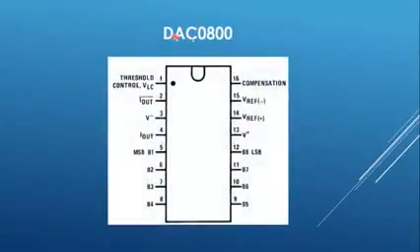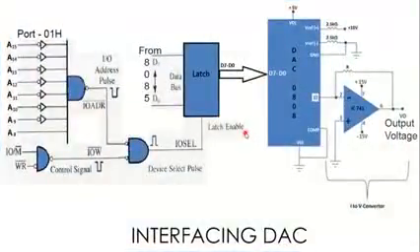Digital to analog converter: B1 to B8 pins are used for input of digital data. I out gives the equivalent current. Reset. Rest of the pins are for reference voltage. As DAC does not require any control signal, it can be directly interfaced with 8085 through a latch.